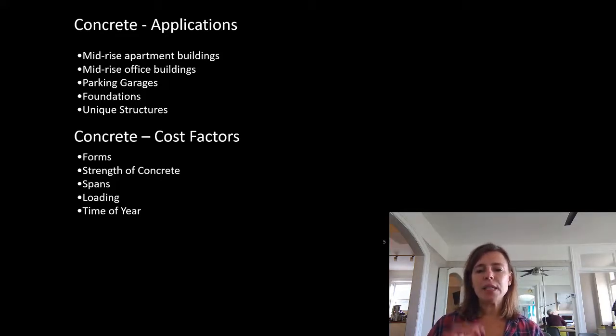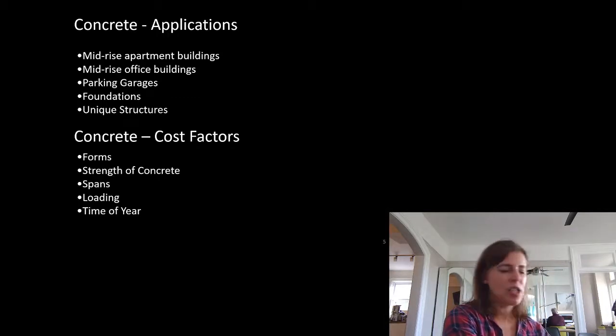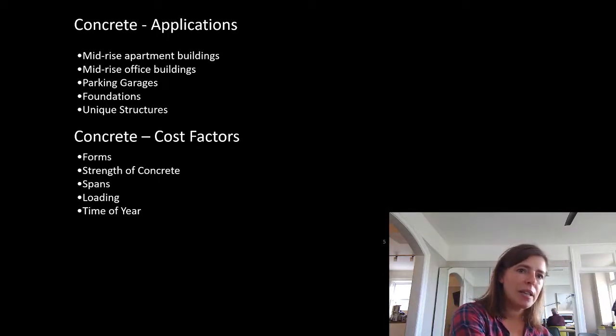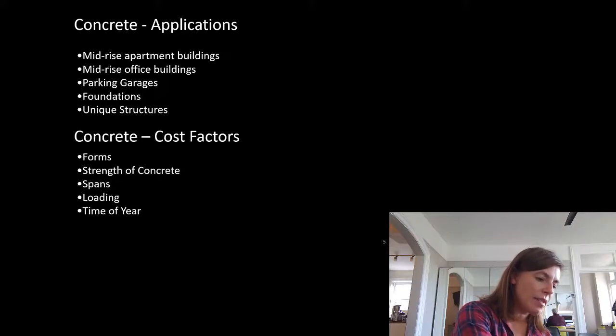But when we get into the really high-end concrete, cost can be a big factor. So if we're doing a 60-story building, some of that concrete needs to be really high strength, or maybe we need special additives added to it to make it cure faster, or deal with some of the spalling issues or finish issues. That can add real cost. So I might even change that in slide 5. I might add to cost: concrete mix or additives.